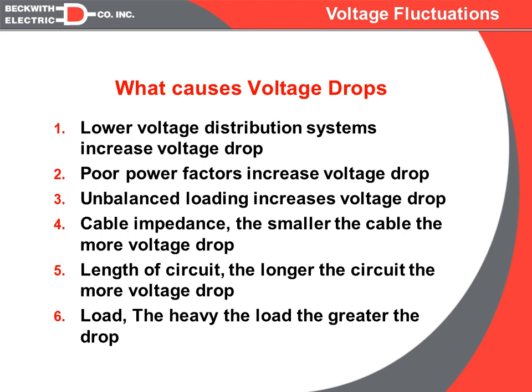That being said, on a typical distribution circuit, reactive current will typically cause a 3 to 4 times greater voltage drop than real current. So if we can reduce the amount of reactive current that flows through the system, we will reduce the amount of voltage drop. So if we can clean up our power factor to where we only have real current flowing at unity, then we will definitely greatly reduce the amount of voltage drop.